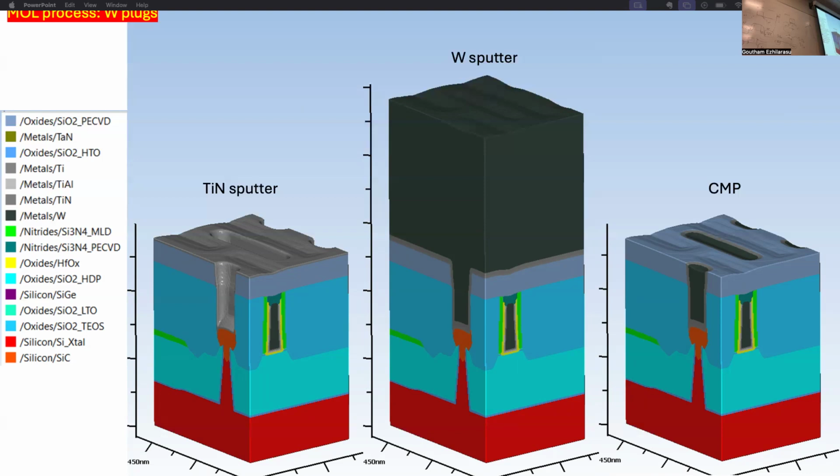You're also polishing oxide at that time. Yeah, oxide is just soft. You're just polishing. See, you are asking, did I stop? No, I didn't stop on this oxide. It's not a polish stop. It's a timed CMP. I'm polishing the oxide also, actually. Okay.